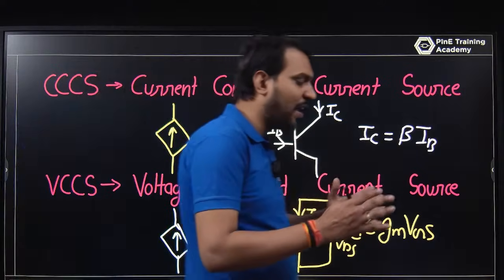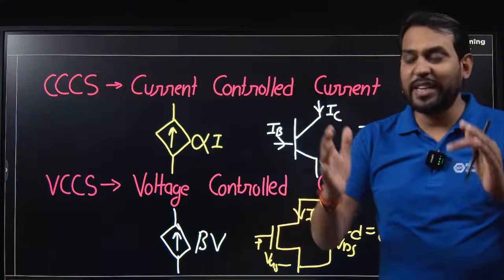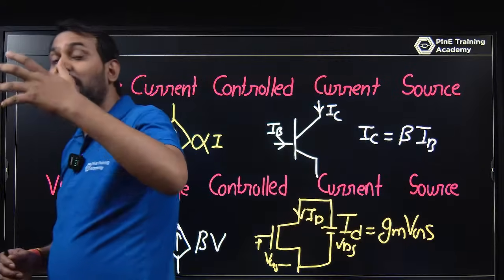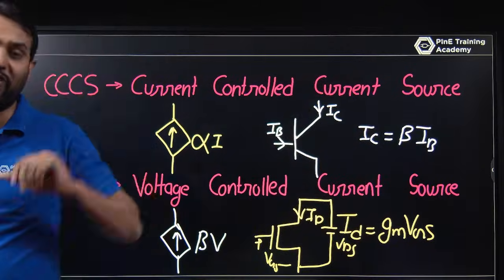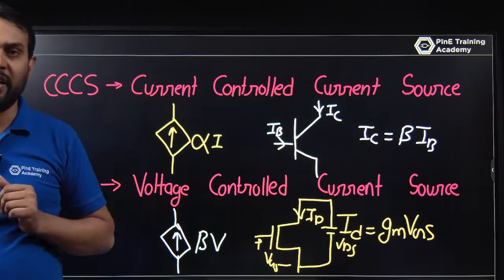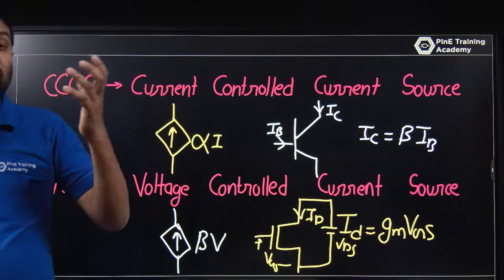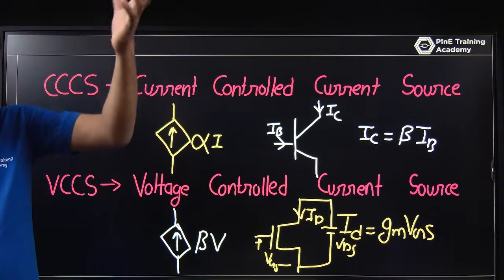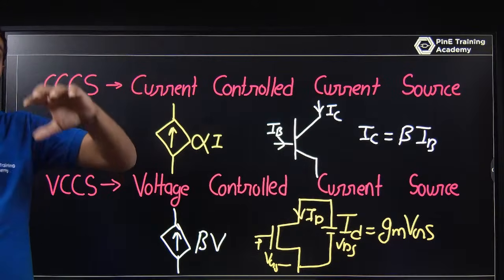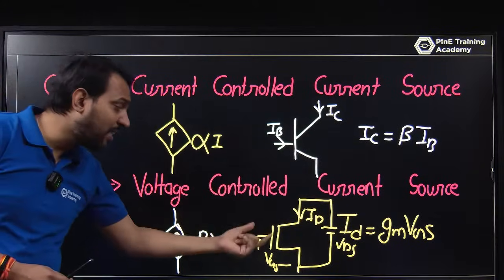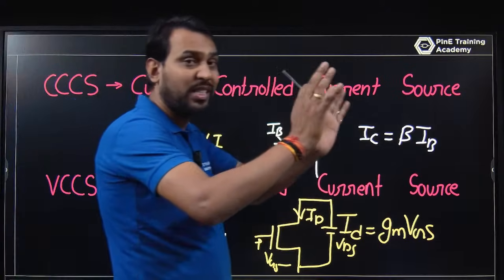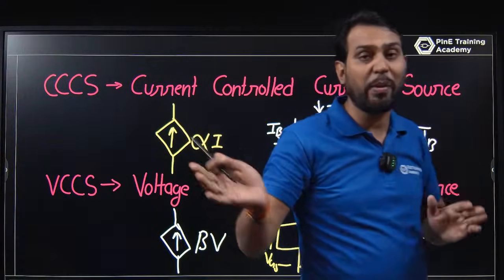So everywhere I am saying that resistor, capacitor, and inductor are not useful for this type of understanding of the amplifier or sensing circuit. For understanding an amplifier, op-amp, amplification, ADC, or DAC, there is a requirement to analyze the dependent source. You convert your whole circuit in terms of resistor, capacitor, dependent source, and independent source.